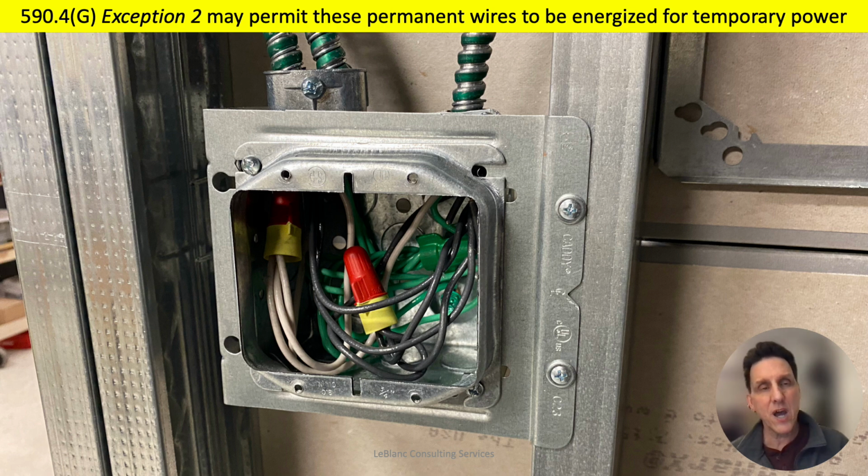Now at the top, my wording says exception 2 may permit these permanent wires to be energized for temporary power. I'm pretty sure the intent of exception 2 is to apply to a box just like this on a construction site where you have the branch circuit wires completely inside the box and there is a plastering, and you might want to energize this permanent wiring for temporary power or temporary lighting, and you can do that if it's GFCI protected. But I have a couple questions.